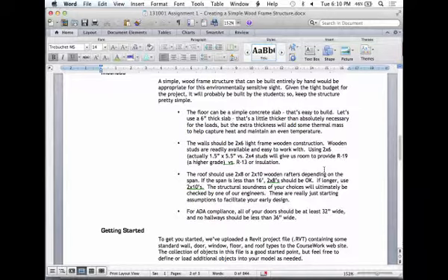These things, spaced out about 16 inches, will be either 2x8s or 2x10s. When we indicate the spacing between them, we'll say that'll be at 24 inches on center, and that just means that there's one of them every 24 inches. It's probably going to be something like this.